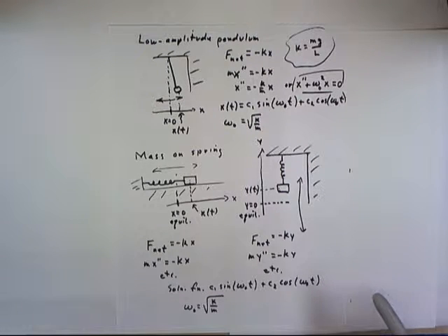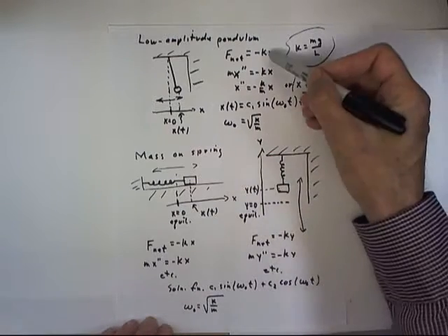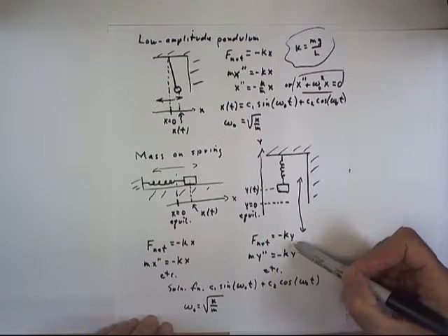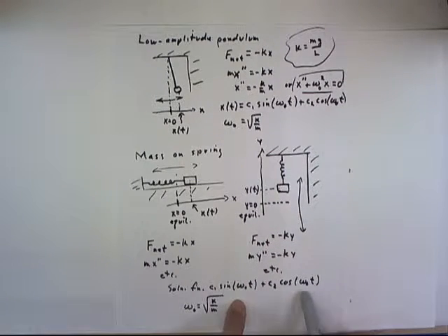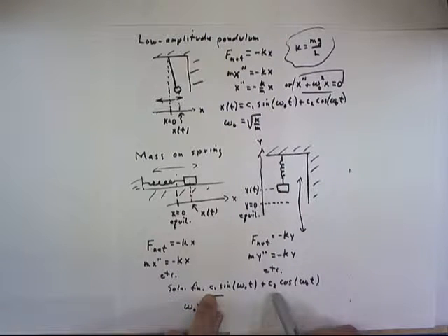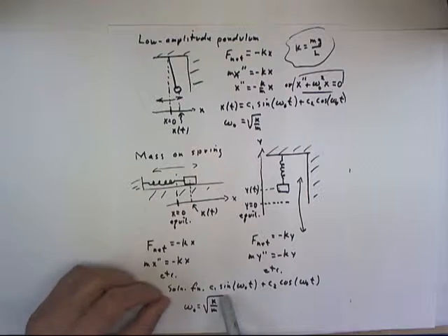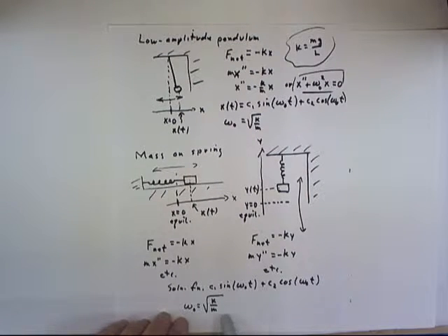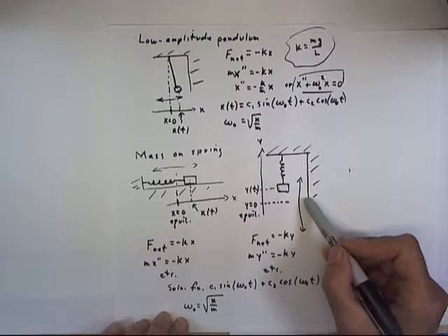In the ideal case, where we have no external forces, only the restoring force acting on the system, this is our complete solution. Depending on the initial conditions, we can evaluate C1 and C2 to accommodate initial conditions of position and/or velocity. We should pretty well completely understand how that works at this point for the ideal system.